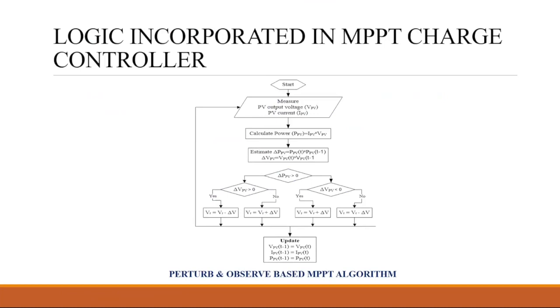If we have to move to the maximum power point, what do we have to do? We have to move here, right? We have to increase the voltage, and increasing the voltage means we have to increase the duty cycle. So, for the case of a buck converter, does anyone know the relation between the output and the input voltage? No, don't worry, it's okay. This is the equation.